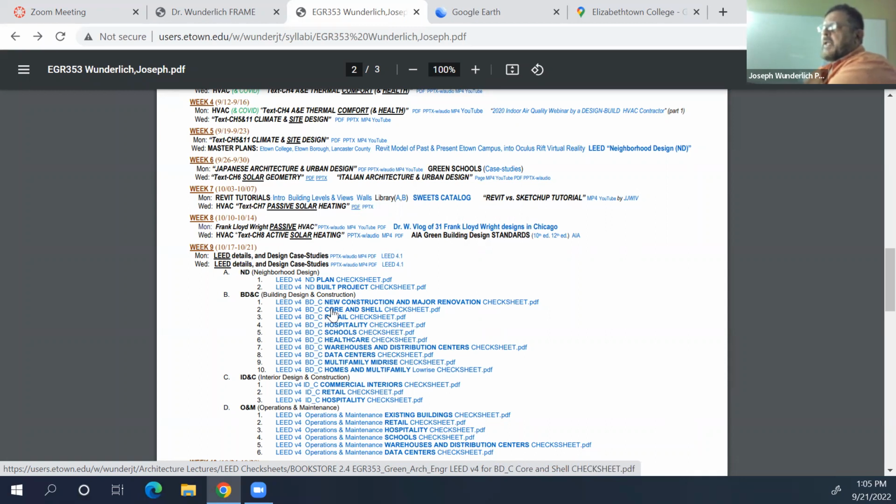So you would make a shell, you make a building that doesn't have any internal walls, other than the utility core. It would have elevator shafts, plenum spaces, a main plant for heating and cooling, electrical distribution, main trunk lines above the ceiling grid, and a ceiling grid not complete but mostly up. And then you would rent to different tenants, and you would give them an allowance called a tenant improvement allowance, is so many dollars per square foot, and then an architect for space planning specialty would come in and fill it in.